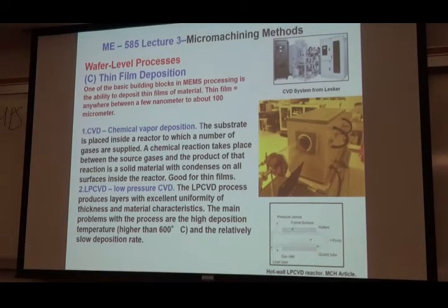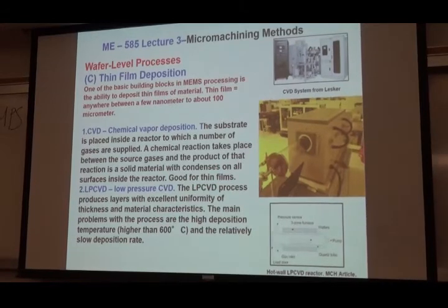But we know you take gas, high temperature or high energy. Okay, you're energizing it. So at the molecular level, actually, you're creating high temperature at the minute level. The overall temperature may not be that high. So that creates plasma. So I could take my chemical and turn it into a plasma, and it deposits much nicer. Okay, I could get a very good film. So that's called PECVD, and we could do it in our lab.